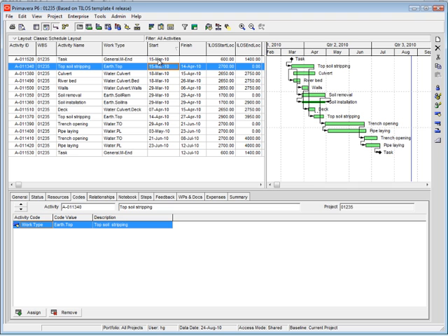Milestones are converted into start or finish milestones inside Primavera. Activities are converted into activities inside Primavera. Hammock activities are converted in level of effort tasks.